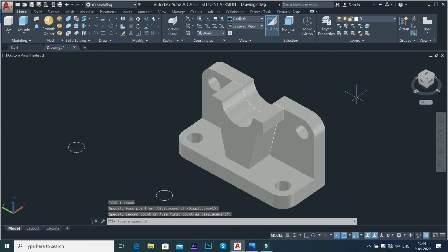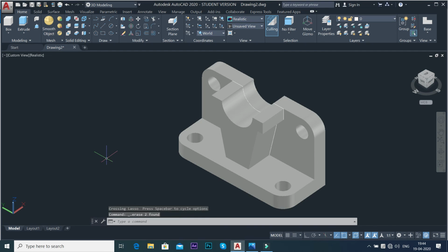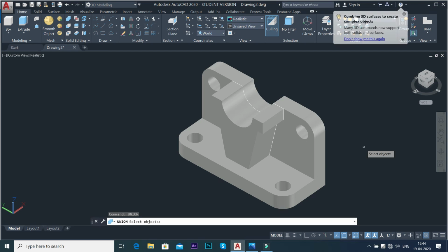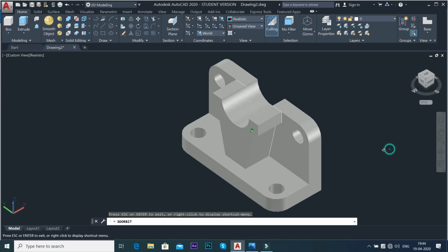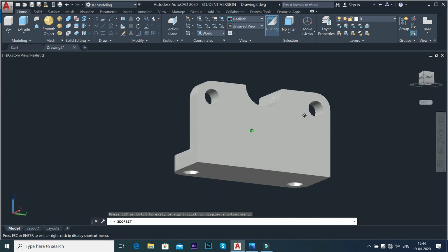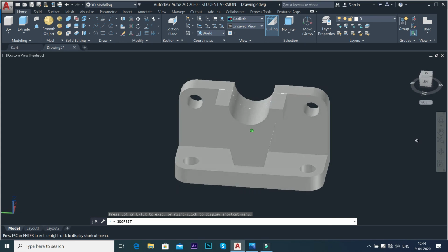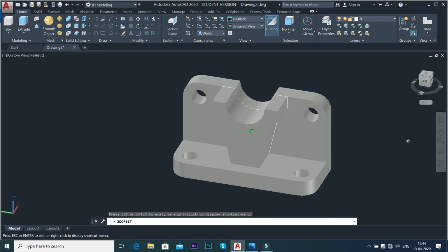Right now, as you can see, these two circles are no longer required, so I will delete them, and these two objects are now separate objects, so I can use the union command for joining these two 3D objects. So union. Okay, enter. Select the first object, select the second object, and click enter. Now it's a single object. You can actually orbit it. I hope our drawing is complete. Okay, it's an interesting one, and hopefully you have understood how to create this type of complex mechanical drawing.